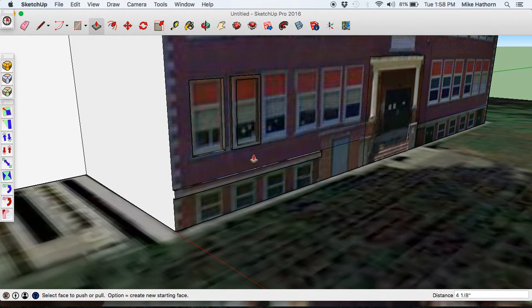If I use supports, it'll make a mess. I want to try to print as little as possible with supports. So I'm going to use the push-in method. And once you make one that you've pushed in, you can click once, touch the other window, and click again. And that'll make sure that window is the exact same depth as the other. And then once you've done it a couple times, you can just double click and it will automatically put it to that window.